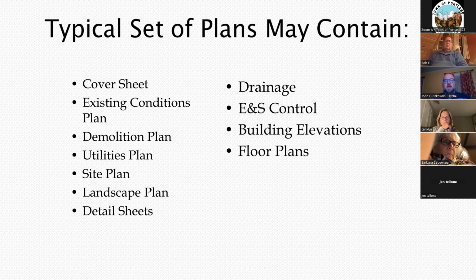If you have a dense clay soil that doesn't drain well, it doesn't matter that it's an acre wide. If you're dumping all your stormwater on it, it's just going to stay there. It's not going to go into the soil. Or if you've got really nice sandy soils, they'll infiltrate fast and you don't necessarily need that much square footage to drain whatever area it is.